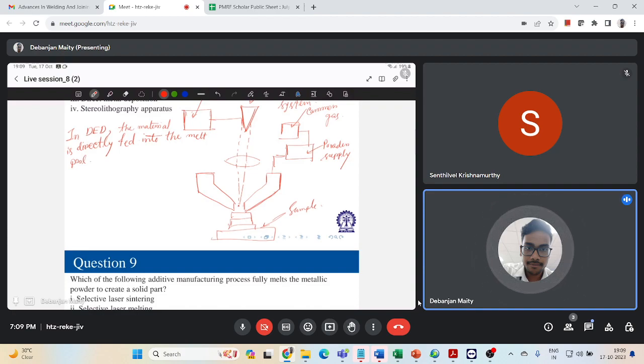This temperature gradient and the subsequent cooling rate are directly linked to the local microstructure development of the melt pool. So people are working on those areas also. And for the EPBF system, the electron beam powder bed fusion, the powder bed platform is heated to 50% of the powder melting temperature to greatly reduce the thermal variance experienced during printing.